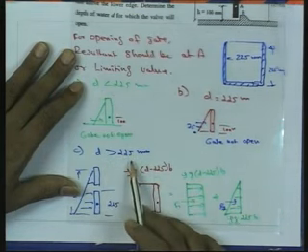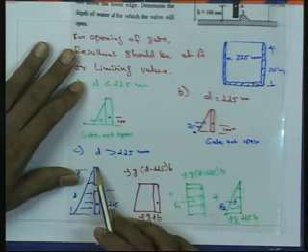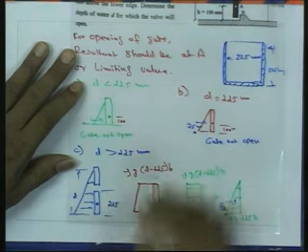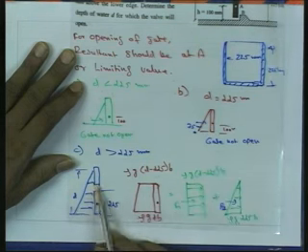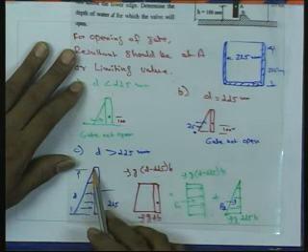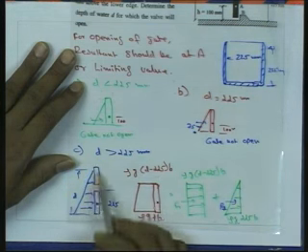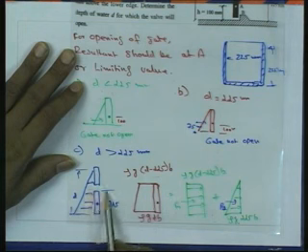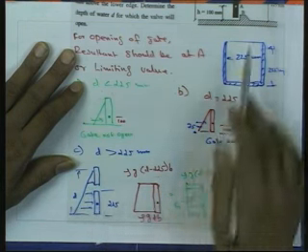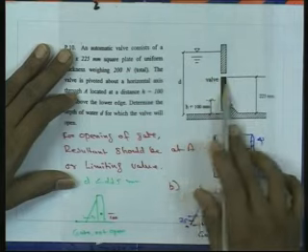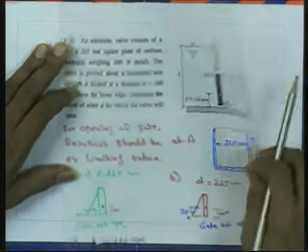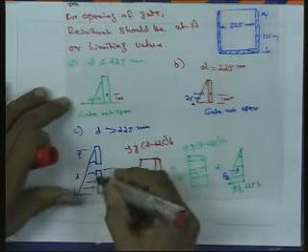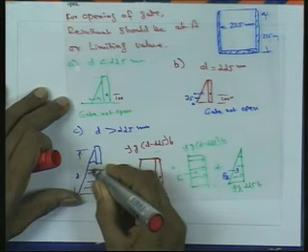So, the third case we will consider is when D, the depth of upstream water level, is greater than 225 millimeter. In this case the pressure distribution can be drawn like this with respect to the gate. The downstream depth is up to 225 millimeter, and above that the pressure distribution with respect to the upstream water will be extended like this. This is the particular location where the gate is located, where the downstream height coincides with the upstream height.